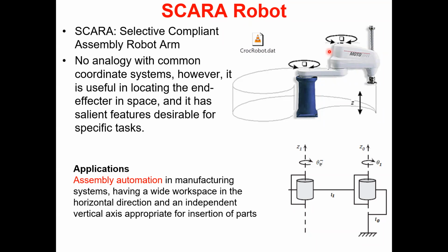Therefore, the motor doesn't actually see the nonlinear change of the gravitational torque. It will see something, but that is a constant thing. It's not a variable depending on the position, and it's not a nonlinear thing either. So it's a good thing to have vertical joints.